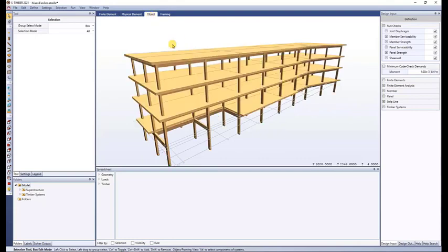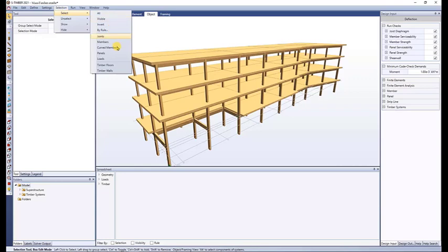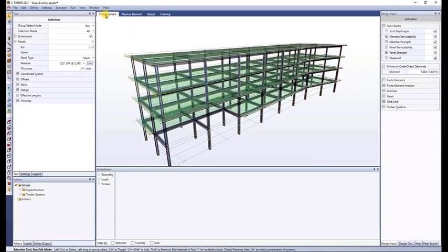You just need to go to the object view, make sure you select all the panels, then you can move on to the final element view, and in the mesh option, you can change the element size. Instead of 1 meter by 1 meter, you could do half of it. And the changes will take place.